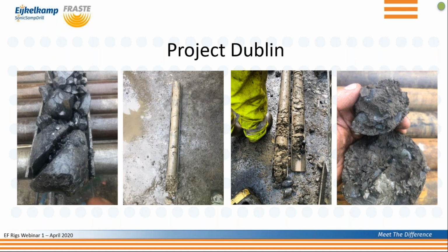The only time, being hand-on-heart truthful with you, that Sonic can't compete with cable percussive is your one borehole, your one 10-metre borehole or your one 15-metre borehole, because we just can't get in and out in a day with a lorry cheaper than a cable percussive rig.